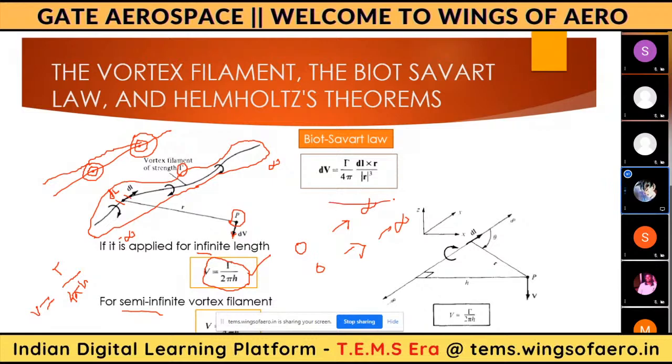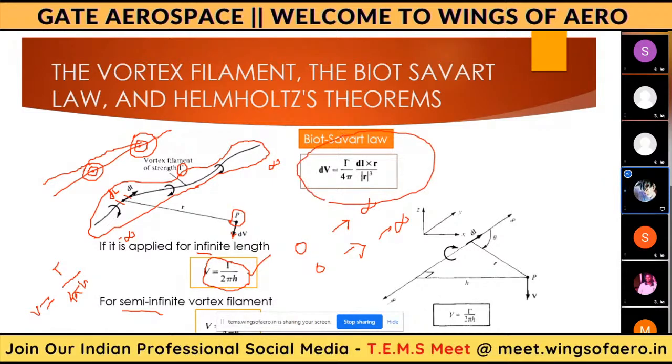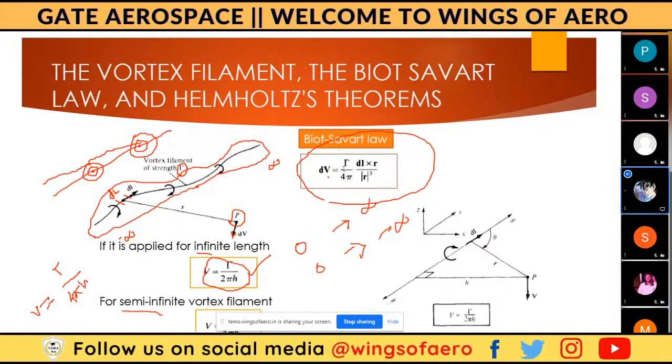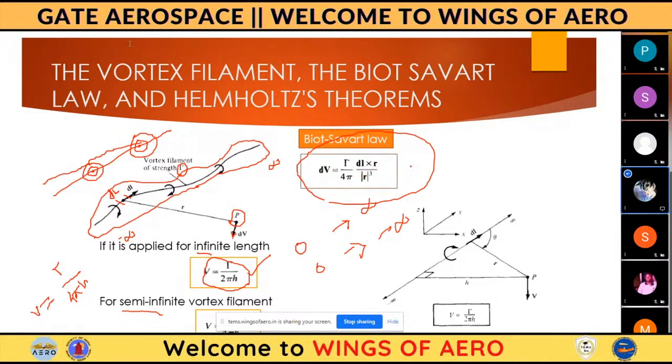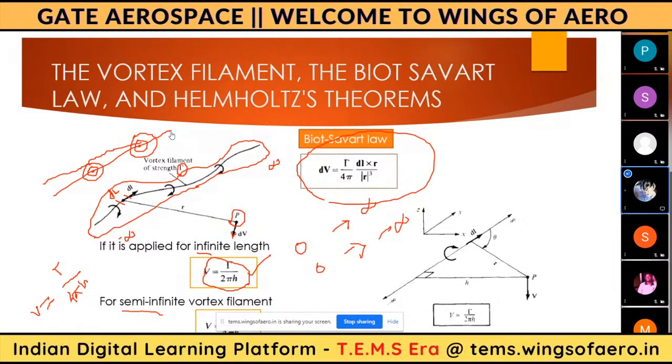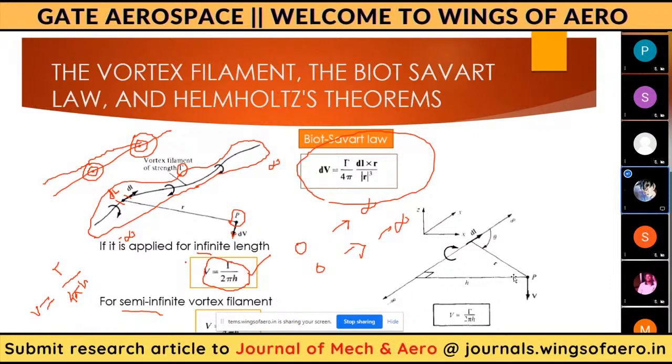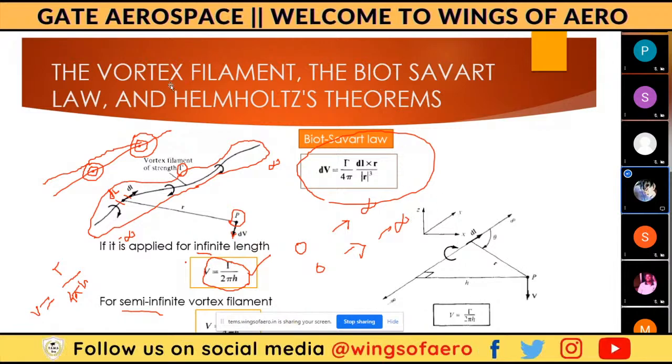So this is the Biot-Savart law. We can apply this Biot law to a current carrying wire also, but we have no need of that here. From the Biot law, dV equals gamma divided by 4 pi into dl into r divided by r cube. This is taken from the vortex filament, but we need only these two equations: one for infinite length, and another for the vortex filament of semi-infinite length. Have you noted down these two formulas, guys? Yes, sir. Okay, fine.